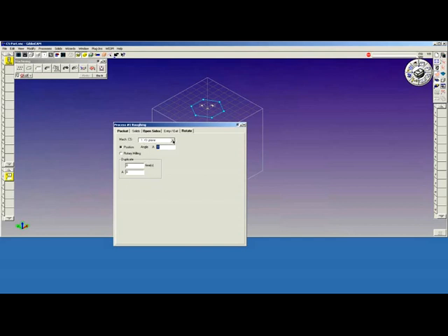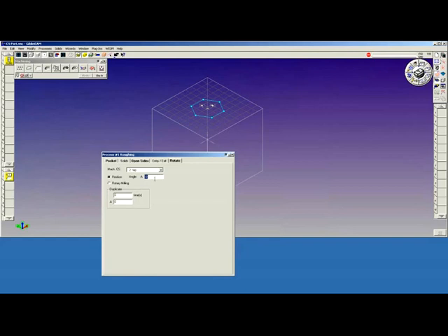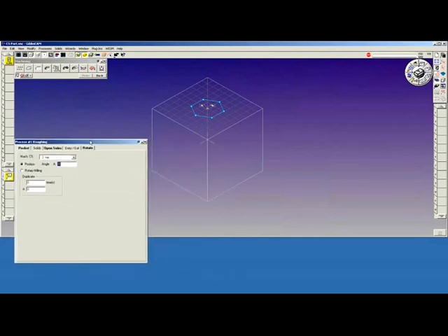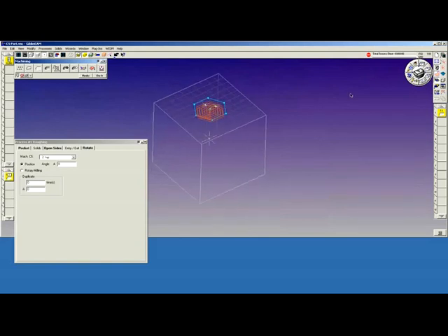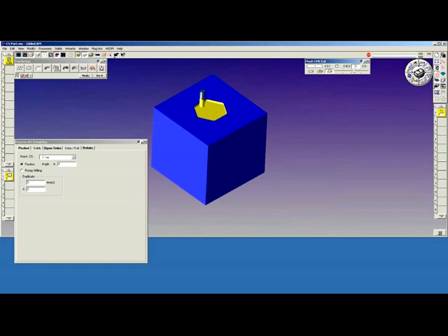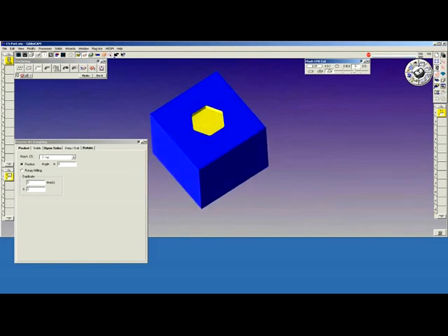If I go to the pull-down menu, I select the top CS. This will localize all of the values to that coordinate system. The angle is 0, and let's cut it at 0 to illustrate what happens. Put this out of the way here. Select the geometry and do it. The operation appears on the right, the tool path appears on screen, and if I render it, I get the machining.